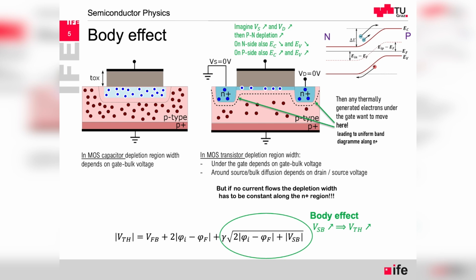But this is only related to two terminals, the gate and the bulk. And so it's only dependent on the gate-bulk voltage, as well as all the things listed before. That means gate oxide thickness, substrate doping concentration, and gate material, which also contributes to the flat band voltage.